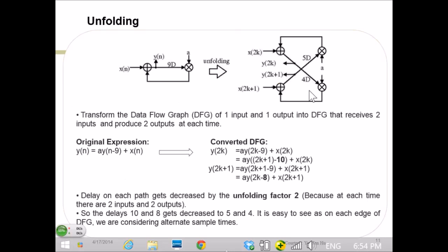And so basically I went over this part one very quickly, but the concepts are very simple in terms of the DSP, the basic concept. The problem comes in when you look at a complex algorithm. There are so many things that you don't know: what part you want to do the folding operation on, what part you want to unfold, what part you want to parallelize, what part you want to pipeline. Because the main requirement is that we want less area and less memory. So when you look at a very complex mathematical formula, it is not very clear how you want to do those operations, how you want to sequence them, or whether you want to change them or not. But the fundamental concepts are simple.